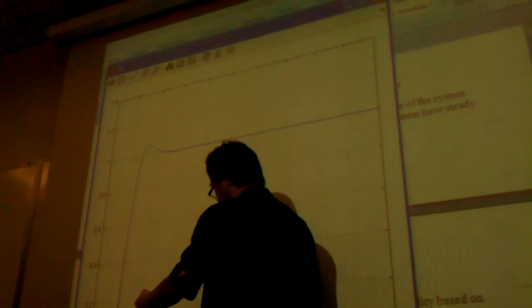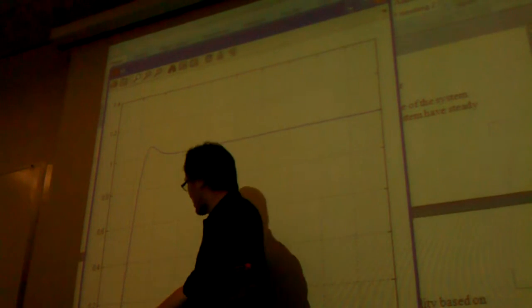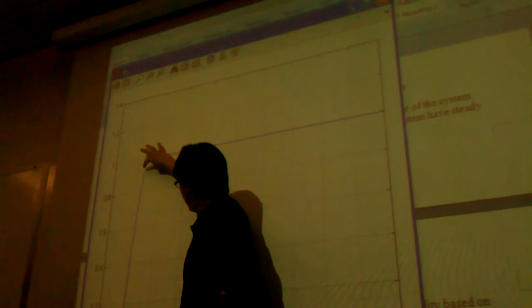And you need to make sure it starts at 1. So your settling time is about 1 second, right? Because you have to count from here to here. So it's about 1 second. Okay? Questions? Yes. How was it worked out? Where did you count from? Because the step time is 1 second, so from 1 second to here, the interval will be about 1 second. Okay?